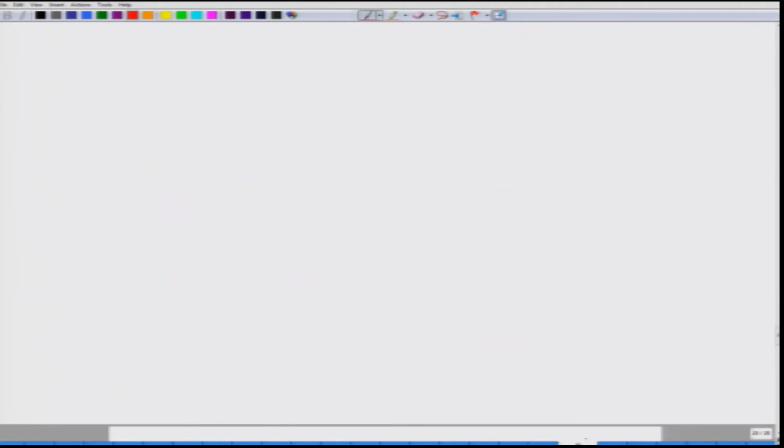Okay. Now, instead of working with free space, which we used just to understand what was happening, we now want to consider what happens through the fiber. Since I am considering the fiber, I know that beta will be some function of omega, correct. But now I am going to assume that my pulse, instead of being just a pulse here, has actually been modulated onto a carrier, and let me take the carrier frequency as omega 0. This is how you normally transmit optical pulses.